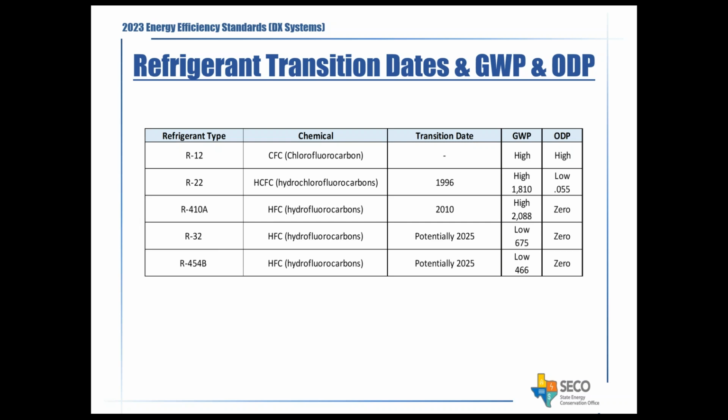So they wanted lower ODPs, but nobody cared about the GWP, or it wasn't defined at that point in time. Since then, more research has been done, and it has been determined that the GWP is a composite that takes into account ozone and other factors. There are still debates on it, but the GWP is the new going standard. You won't see a change in the ODP. People have attained zero ODP before, but now you also have to attain a low GWP on the refrigerant.